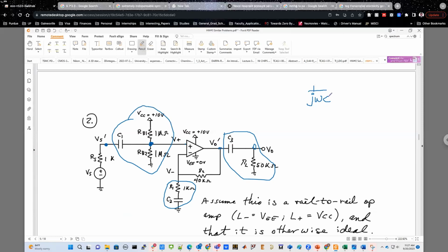In terms of AC, you'll just assume that you have the capacitance in a way that what is AC? Let's just assume infinite frequency. If it is infinite frequency, then the denominator is infinitely large, so the impedance is 0. So in terms of AC, the capacitor is a short, provided that your 1/jωC is very small. In terms of DC, the capacitance is an open circuit. Okay, so that's all we are doing using the RC networks at the input side and output side.